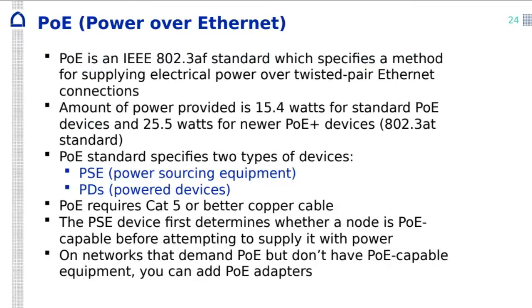We have also PoE, or Power over Ethernet. It is an 802.3af standard. Here you can supply power over twisted pair Ethernet. The amount of power provided is 15.4 watts, so not too much. Okay, and 25.5 watts for the newer PoE plus.